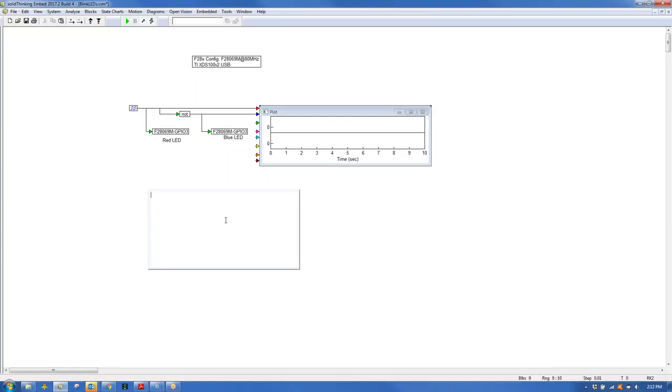Yes. So GPIO 34 is defined as the red LED, and GPIO 39 is defined as the blue LED. This is in the Texas Instruments documentation. You actually have to read it to discern this, but I'm just going to tell you that's what it is. It won't change. So if you're using these GPIO values, you will light up the red and the blue.